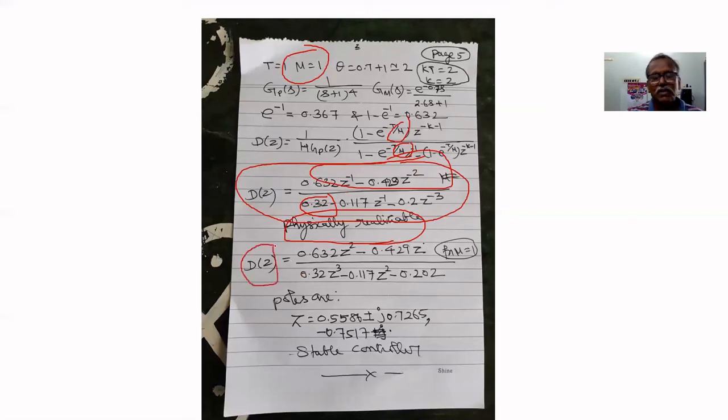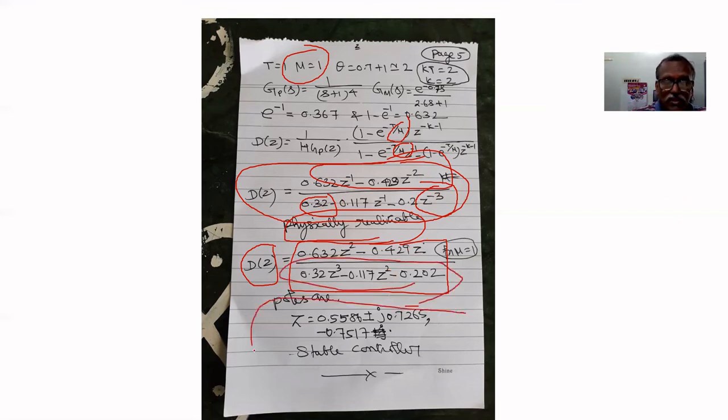In the denominator, the lowest degree is z power minus 3. Multiply the numerator and denominator by z power 3. You will get positive powers of z in the controller. This is convenient to enter in the Simulink block. Now, if you check the roots of this denominator polynomial, they are within the unit circle. Therefore, it is a stable controller.